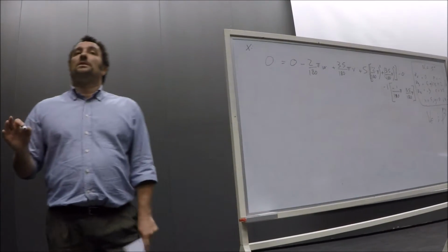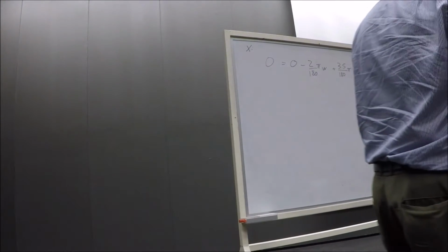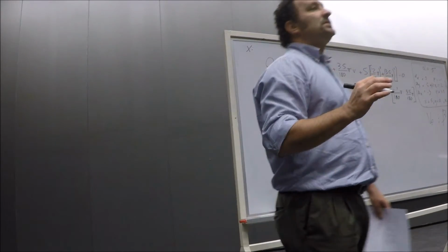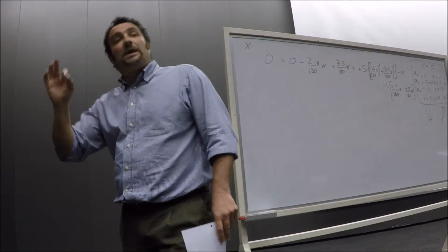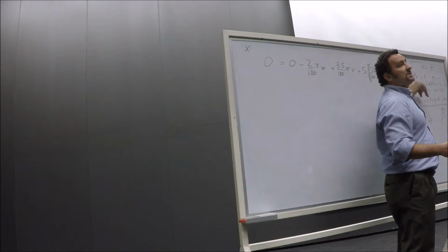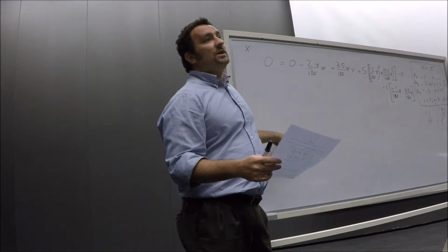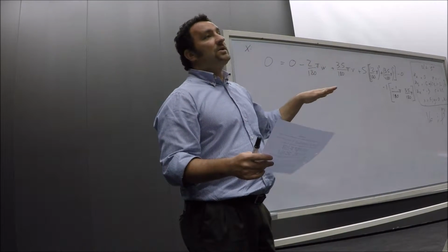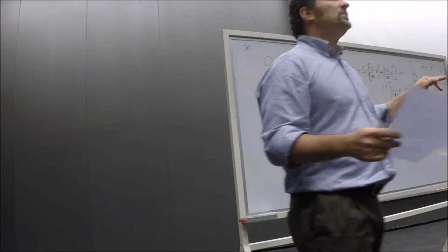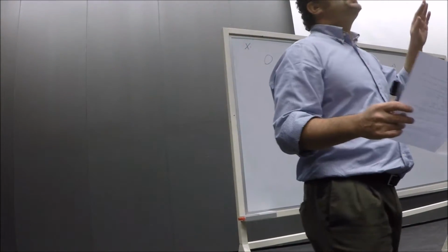Okay? Everything clear? Yes? Because you're in steady state, so there is no acceleration as measured on the aircraft. Okay, because here you have absolute acceleration as measured from the ground. But the terms u dot, v dot, w dot are the accelerations measured on board the aircraft, and they are 0.